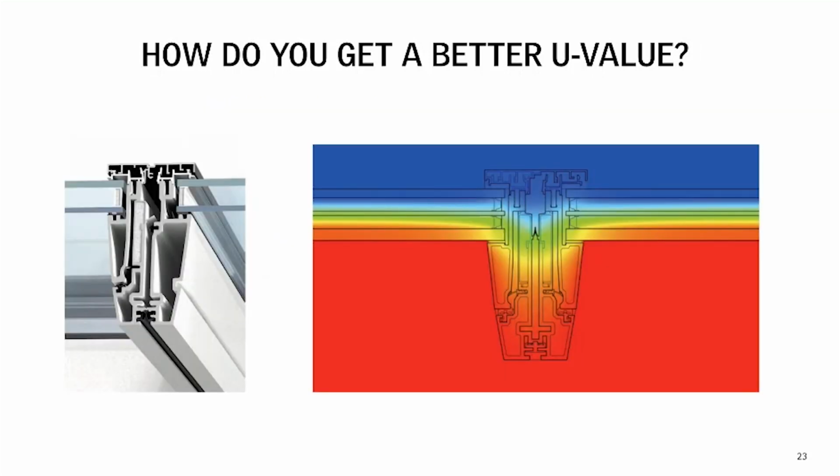Now the second part that's included in the U value is the frame. Now the frame is super important because I'd say in North America and being involved in the fenestration side of things, we've been able to get better glass, coatings and better spacers. And the next big push, and this is happening more so in some parts of Canada than others, but the next big push is more energy efficient frames.